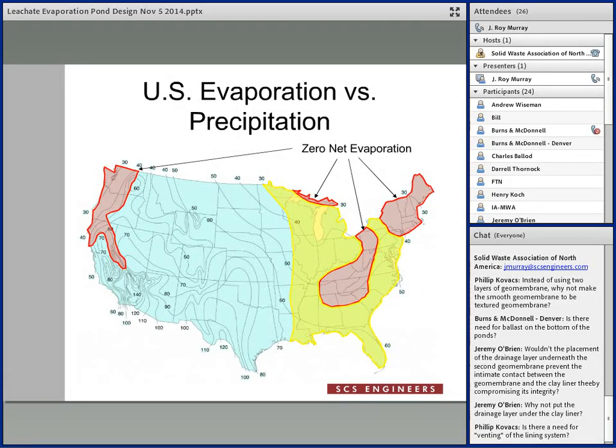We certainly have those kinds of issues when we're building temporary rundown channels off of landfills, and you're getting gas underneath it, and all of a sudden you've got a big bubble underneath your geomembrane-lined rundown channel, so we do have to do the venting on that. But in this case, because it's built off of the landfill, hopefully in an area where you don't have a lot of gas trying to get up through there, there hasn't been any need.